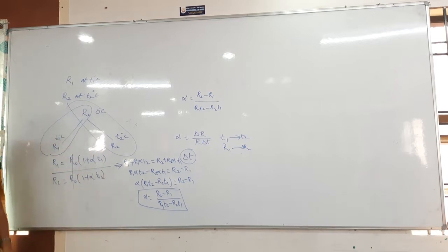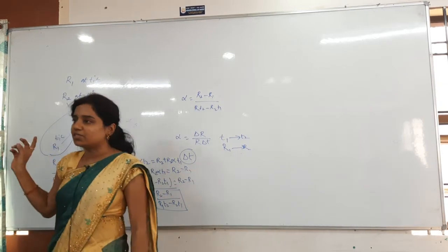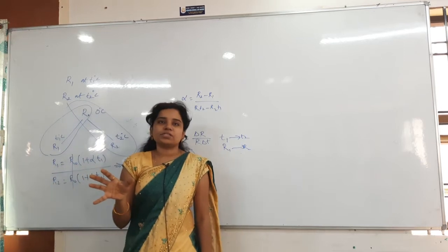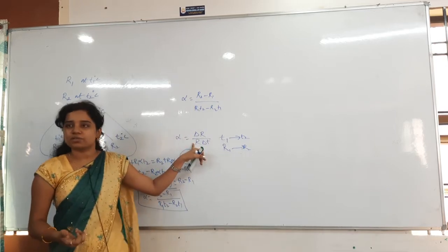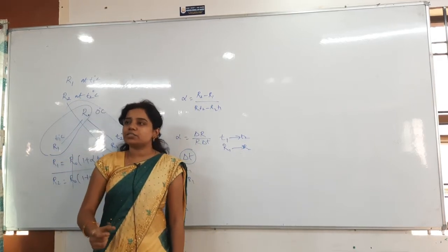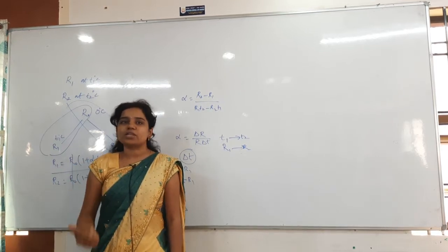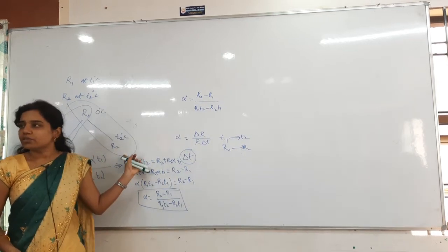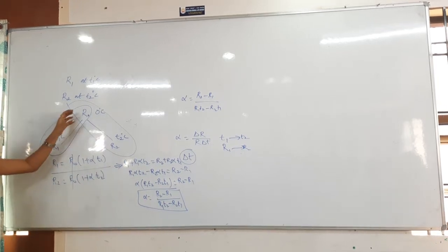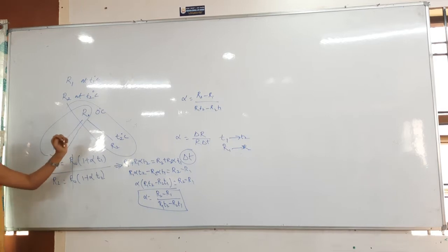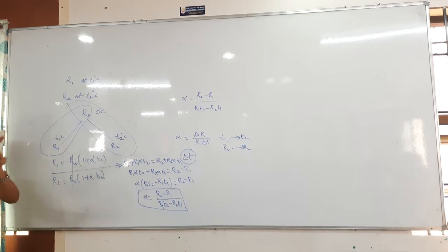The minus signs cancel anyway. Now, you have to make the differentiation between this formula and that formula. That is important. Whenever they say the temperature is rising from so and so value, immediately use this one. Whenever they say that at a particular temperature the resistance is R1, and at another temperature the resistance is R2, then find the alpha value using this formula. The initial resistance we don't know, so I cancelled it here. At 0 degrees Celsius I take the resistance as R0. From that, at T degrees Celsius, the same wire's resistance increases.